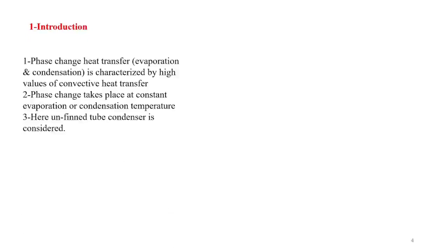We know that this category of heat exchanger, we call it phase change heat transfer equipment, where evaporation or condensation take place. We know that condensation and evaporation are characterized by very high heat transfer coefficient. In addition, condensation and evaporation usually take place at a constant temperature.